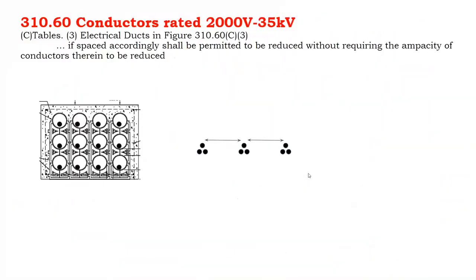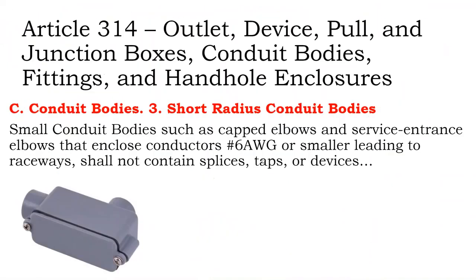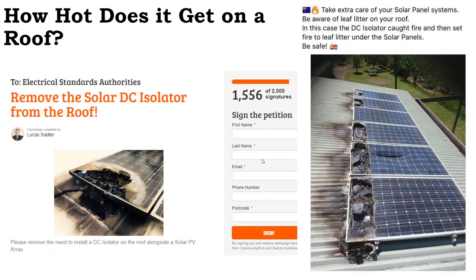And so the rooftop isolator boxes in particular, especially when you're not using specialty solar high rated temperature devices, you're just going to the store and buying something off the shelf, you might have a temperature mismatch, at which point those terminals become the hottest part in the system and can smolder and catch on fire.